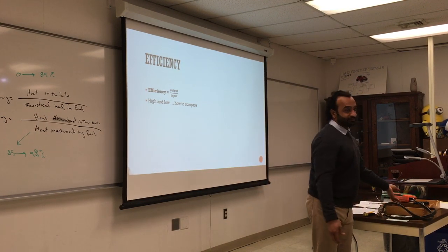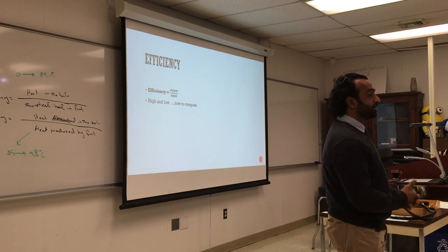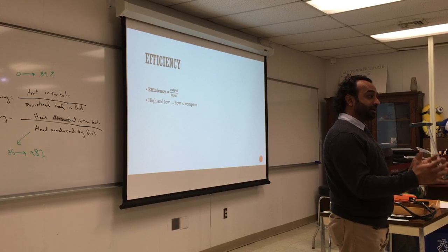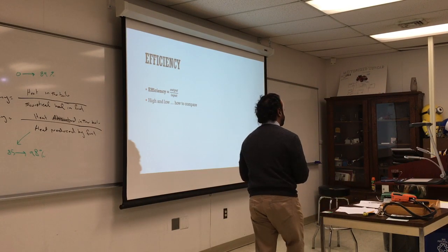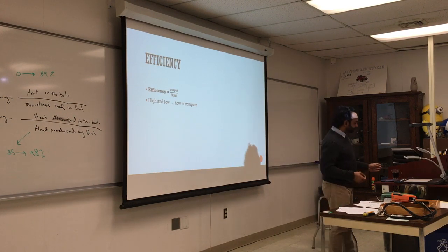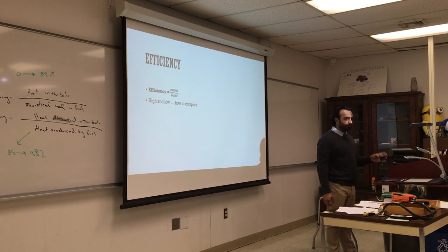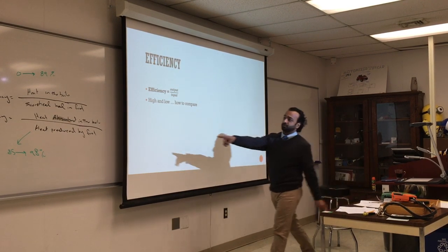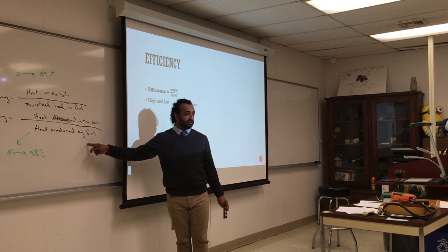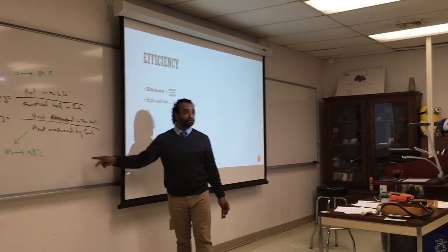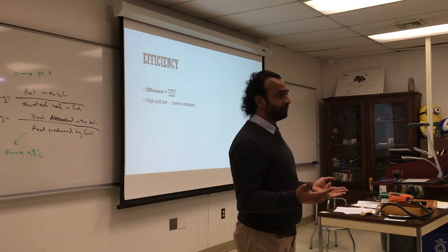For old boilers, you can let it go with 75. It's not gonna do better than that for combustion, but it gets better and better. The smaller the chamber, the better, because we contain the flame and the heat, and it will burn in a better way. If you would have a condensing boiler, for example, that's pretty high efficiency, right? Not combustion, thermal efficiency. It will say 97, 99. It's thermal because they are absorbing all the heat that comes out of the fuel.